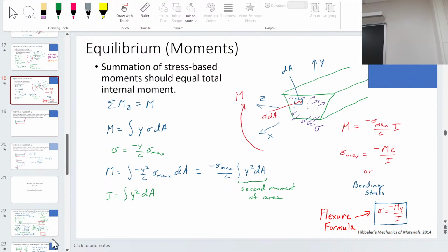I wouldn't do it this way. That's not how you want to do it. What you want to do immediately is go from the right, because this reaction force doesn't take into account what's happening on this side of it. Take a slice: draw the thing with the distributed load and start from the right end.